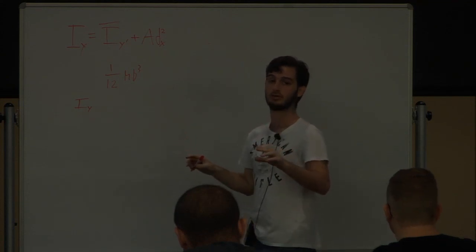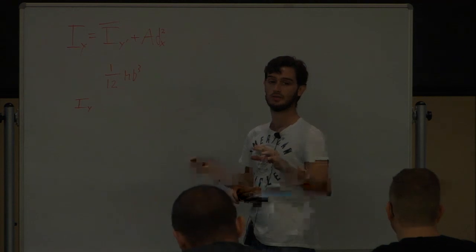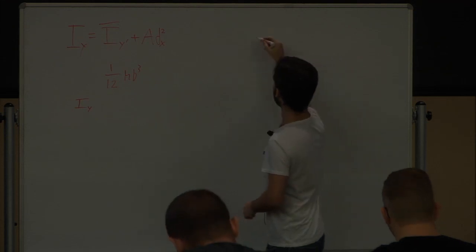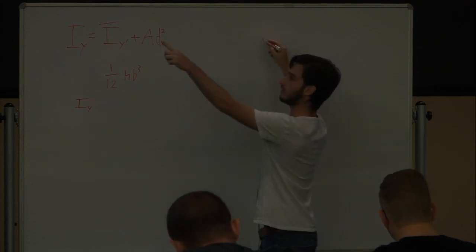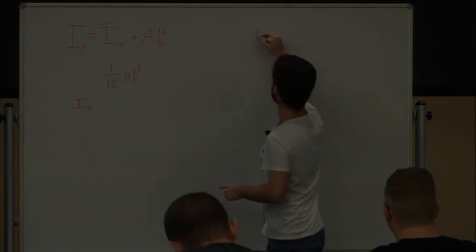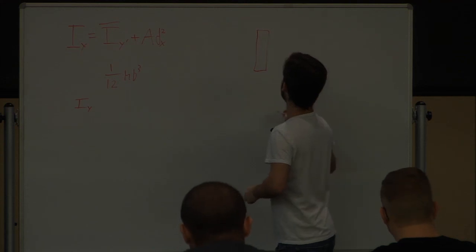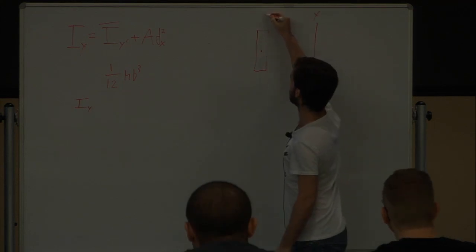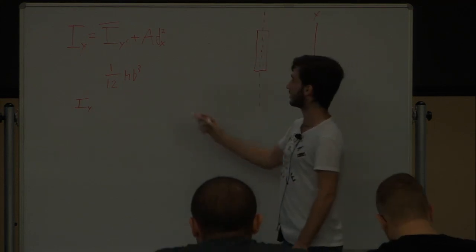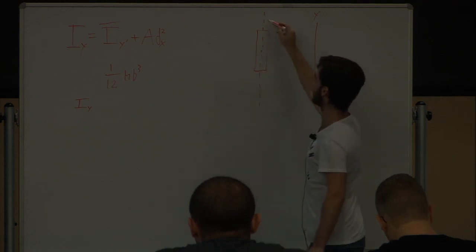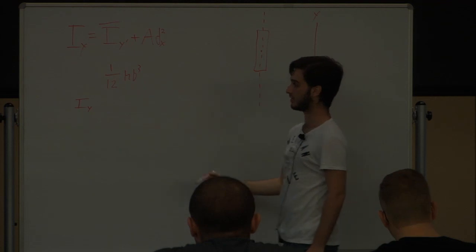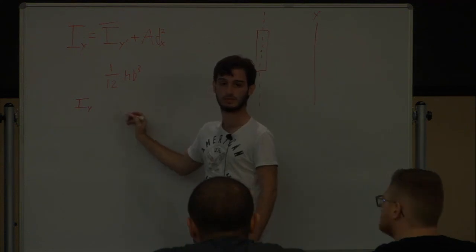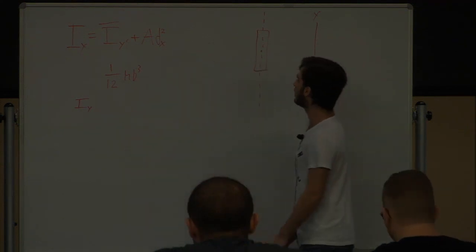So it's a bit confusing. Let's say I take the top left rectangle. I'm measuring the moment of inertia of this rectangle from this axis right here. So the centroidal axis of this rectangle, they give those formulas to you. They're in the back of the book on that same page. Plus the area of this segment times the distance between the centroidal axis and the axis that you're measuring the moment of inertia about.